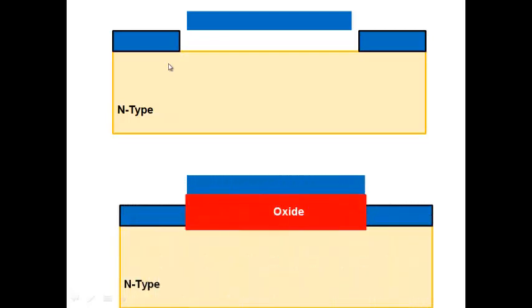Okay. Anyway, so this is the transistor that we have. We said that if you take two terminals and you add a third terminal, place it over your N-type semiconductor, then using this particular terminal, you can control the current which is flowing between these pairs of terminals here. Now, of course, how do you suspend a metal plate very close to the semiconductor? It's not easy, if not impossible, to do that. So what you do is the following.